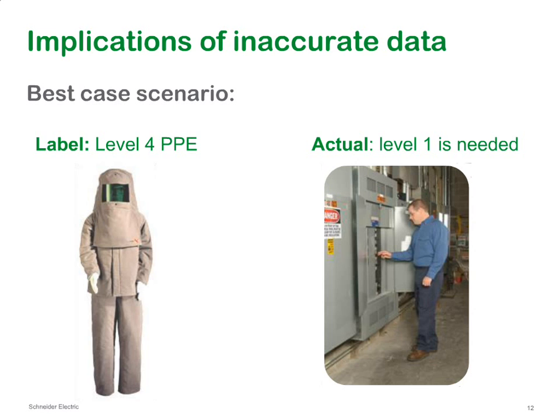And having too much PPE has the hazard of the worker not being able to see properly, not being able to act properly, not being able to move properly, and this could be a very hazardous condition because he could rush during the task. The PPE equipment, especially the higher levels like Category 3 and 4, is very heavy, and it could cause the worker to sweat and have issues, especially in summertime. So this heavy equipment should not be worn more than half an hour. People need to get out of them.